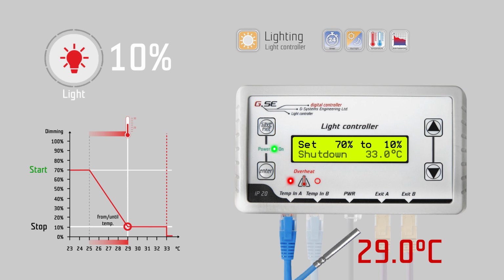The shutdown value cannot be lower than the maximum dim value plus 1 degree Celsius. For example, we set this to 31 degrees Celsius. As soon as the temperature exceeds this value, the lamps will switch off.